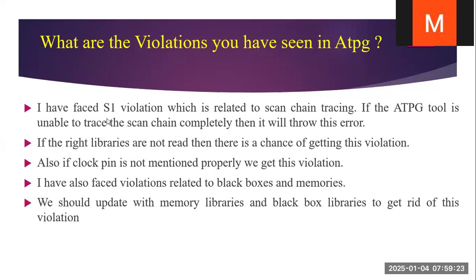Normally in Tessent we call it a T violation. If the right libraries are not read, then there is a chance of getting these violations. Also, if the clock pin is not mentioned properly, we'll get these violations. I have also faced violations related to black boxes and memories. So we should update the memory libraries and black box libraries to get rid of these violations.